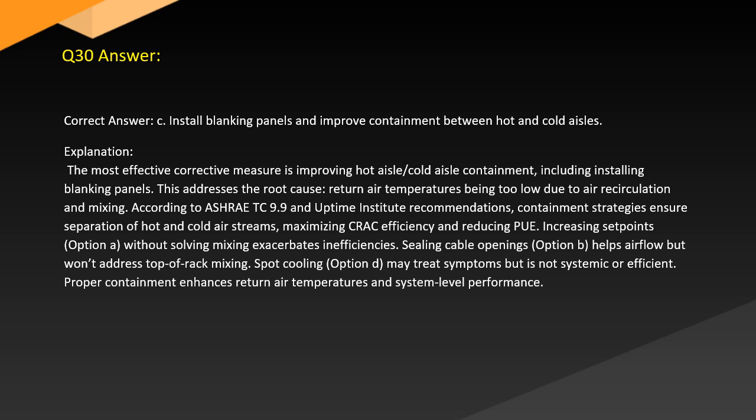Sealing cable openings, option B, helps airflow but would not address top-of-rack mixing. Spot cooling, option D, may treat symptoms but is not systemic or efficient. Proper containment enhances return air temperatures and system-level performance.